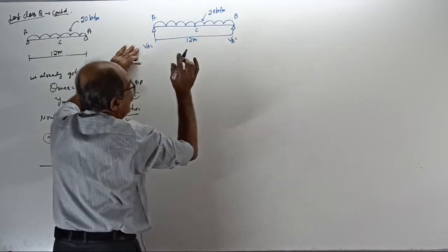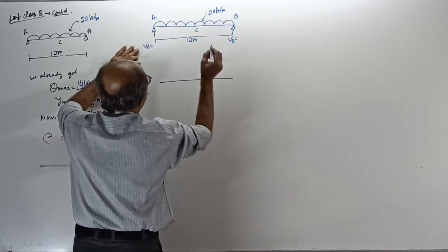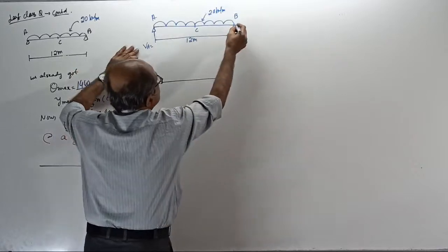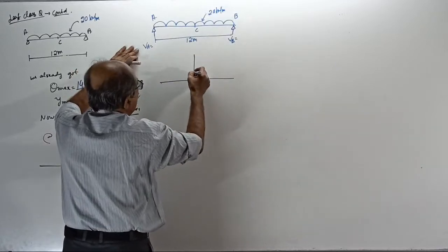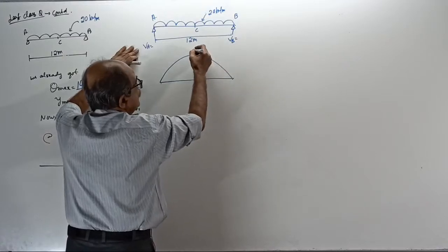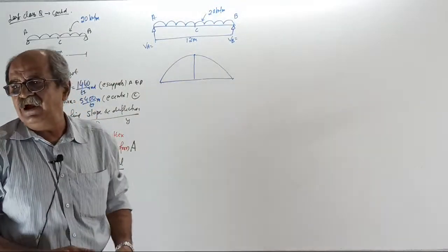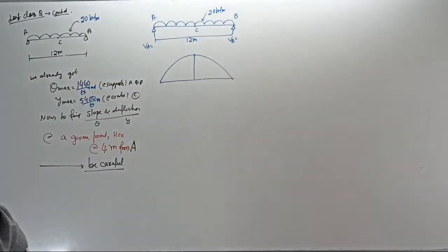We are not calculating because when you draw the bending moment diagram, you know 0 BM here, 0 BM here, maximum here. You got formula WL square by 8. See, and tell me how much this bending moment came? 20. How much bending moment came there?